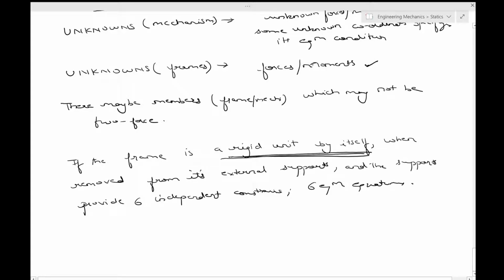So you apply extra constraints to make it rigid, and hence you can then proceed to solve. So for the whole structure, clearly you will be short of such equations because you have artificially added some things. So the support reactions for this case cannot be determined from the equilibrium equations of the whole structure. In such a case, it is usually necessary to first consider the equilibrium of some portion of the system that itself is inherently rigid.